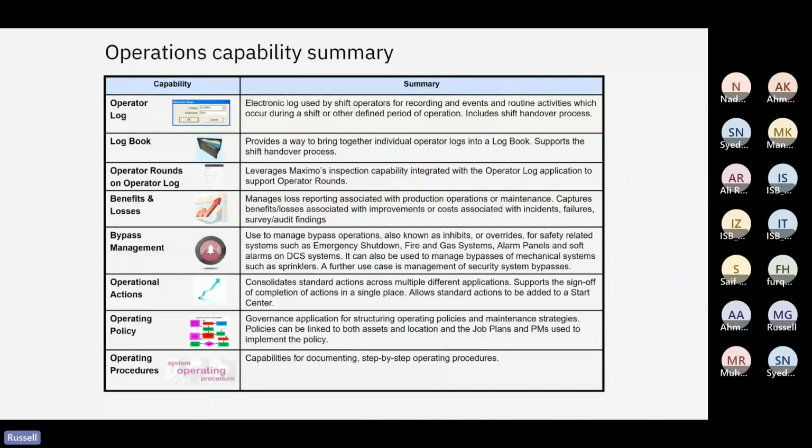One of the important things about a bypass is that you make sure you have the temporary operational procedures in place and have assessed the risk of doing that bypass, but particularly that you restore the bypass when the work that requires it is finished, and that's been an area in the past which has been linked to a number of process safety related incidents.